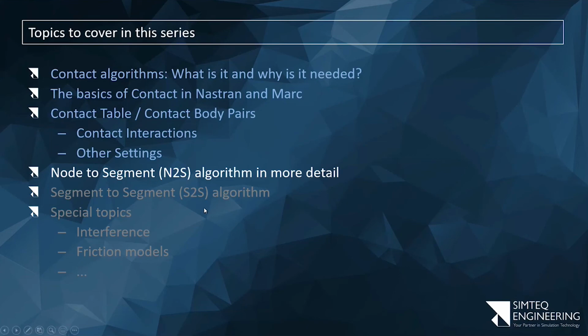Just on that, Dave, if let's say you've got a strength value for the resin or the glue, and you're not too certain about stiffnesses, what you can just as well do is glue it as if it was perfectly glued, and then just separate based on the normal stresses and the shear stresses, instead of using the cohesive elements where you specify stiffnesses in addition. But you tend to get more accurate stress distributions if you actually have a stiffness for that glue.